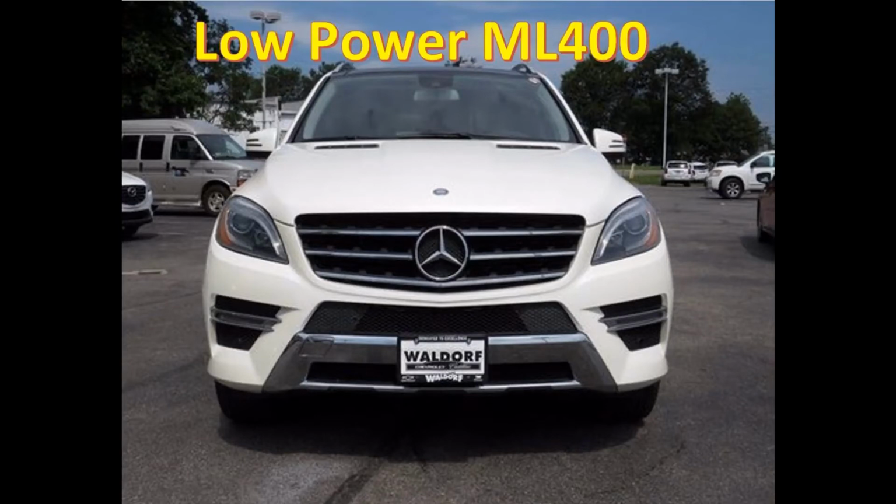So to wrap this one up, we took the car back to the shop, and unfortunately I forgot to shoot video of us testing it. But what we did was test the vacuum hoses and the two wastegates on the turbochargers for leaks. And what we found was the vacuum diaphragm on the driver's side wastegate actuator, so the vacuum pot, had a hole in it. It wouldn't hold vacuum. We couldn't suck the turbocharger wastegate to the on position.